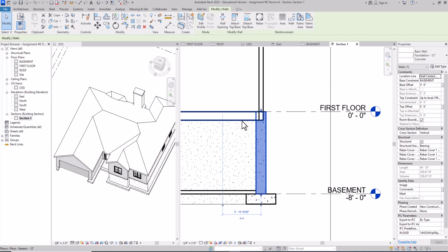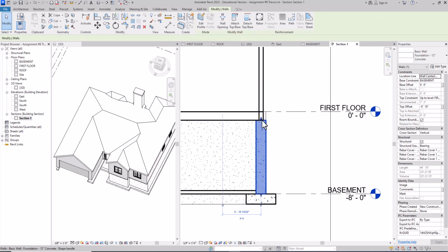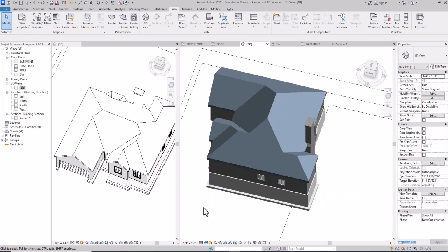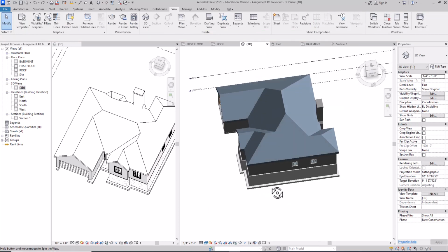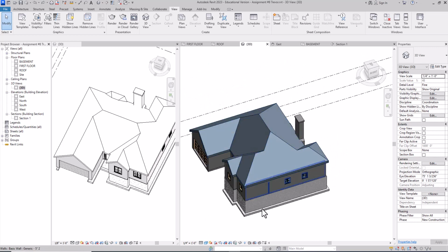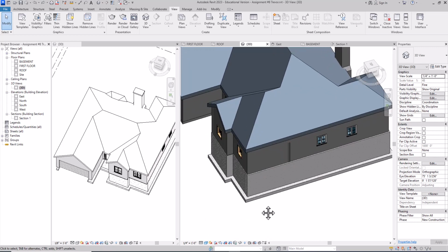As you develop that, and you won't need to do it for this class, you'll see that this offset right here of this wall would come down here a little bit further to pick up the mud sill that you would draw in later on. Okay, so for this week, let's concentrate on getting the roof on and the foundation walls with the footing and the basement floor.